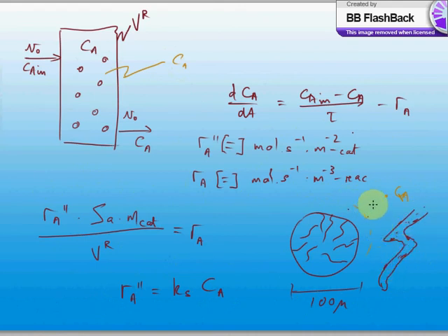So we eventually don't actually know what concentration applies, right? We'd like to be able to use this expression because we have a nice kinetic rate constant and all we need is a concentration. However, the concentration in the overall mass balance refers to the fluid. So that's the concentration in the fluid, whereas the concentration that applies for the actual reaction is the concentration inside these pores here. So we need to correct for this concentration.